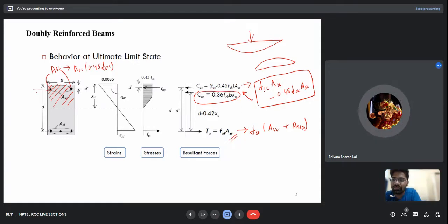Yes, sir. I also thought about that. The reduction in the area is where the steel bars are, so the moment has to be taken from that point only. Yeah, so that is the reason we are subtracting it from Cus and not from Cuc. For force equilibrium, you can do it either way. It won't matter. But for moment equilibrium, it would be a problem. Okay.